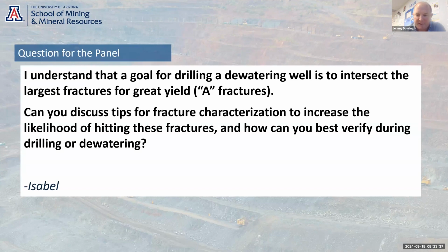And then when you've completed the pilot hole drilling, you can do a prolonged airlift test. So you just pull the drill string off the bottom of the hole and circulate air for a prolonged period. And the sustainability of the flow coming from the hole gives you an indication of the broader fracture network. If the flow rate is sustained, it can indicate that the location is interconnected to a broader fracture network that may sustain a good pumping well.